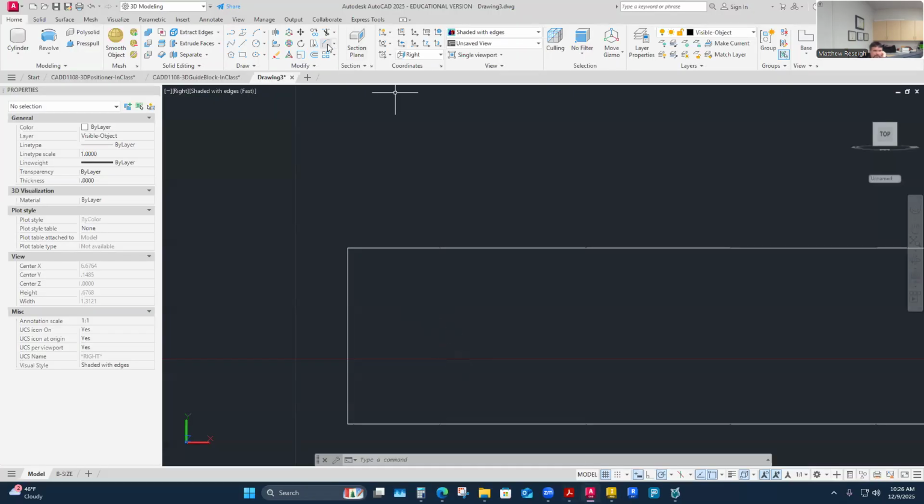So if I select chamfer, let me just see if this works. Sometimes the 3D geometry or your 3D drawings are weird and they don't. Let me see if this one will work. I'm going to set the distance first on a chamfer. It's kind of like picking the radius of a fillet first. I'm going to select my distance of my chamfer, because the default is 0, unfortunately. So I'm going to select my distance as 0.03.